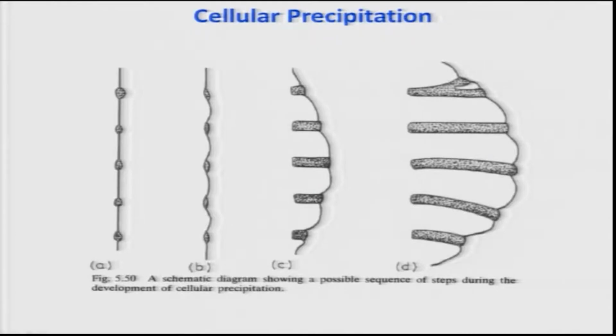You see, this is a cell, correct? In solidification, cells form, and then cells break down. That is why it is called cellular transformation. The transformation equation is exactly the same, alpha going to alpha prime plus beta, where alpha prime is a supersaturated solid solution and alpha is basically the equilibrium phase with the lower thermodynamic excess of solute, and beta is basically the equilibrium precipitate. That means, if you have a supersaturated alpha prime, the beta precipitates out of the alpha, leading to alpha having less solute.